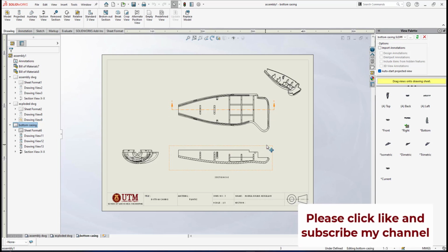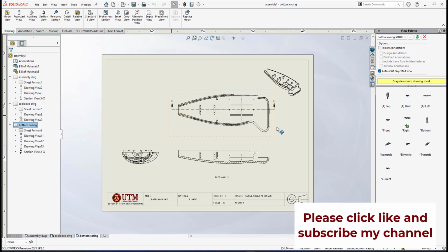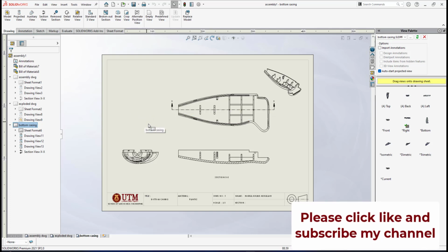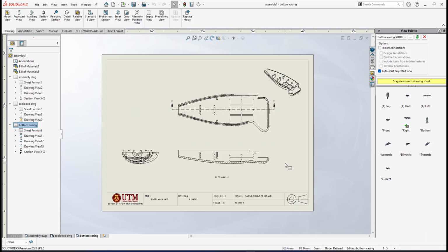Let's say your component is a metal part, for example a long shaft, a bracket, a disc, a hub, and so on. The detailed drawing of each metal part has to be really detailed and complete in dimension, because each detailed drawing of those metal components will be sent to the machinist at the manufacturing floor. The machinists will read your drawing and they will do either lasing, drilling, bending, stamping, milling, and so on, because all these types of machines are for metal parts. So the detailed drawing of a metal component has to be really detailed and complete in dimension.